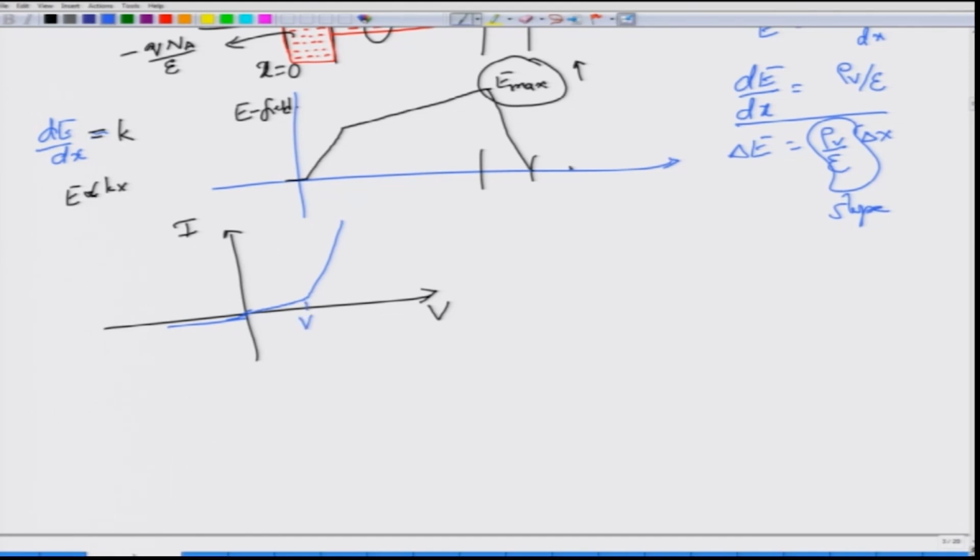There is this cut-in voltage on the positive voltage axis. So, if you are forward biasing, you are going to get this. This is for the case when there is no illumination. There is no illumination, therefore, this current can be thought of as the dark current. What is dark current? What is dark about it? It is simply that there has been no optical input here. But what would happen to this curve when you actually reverse bias and apply a certain amount of optical signal?